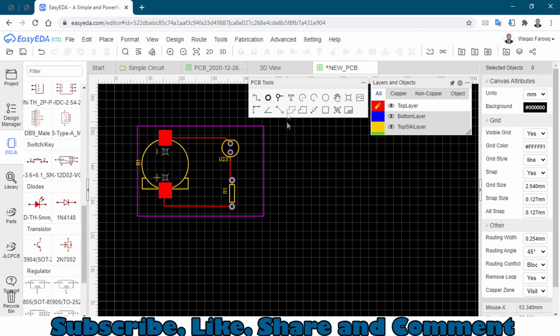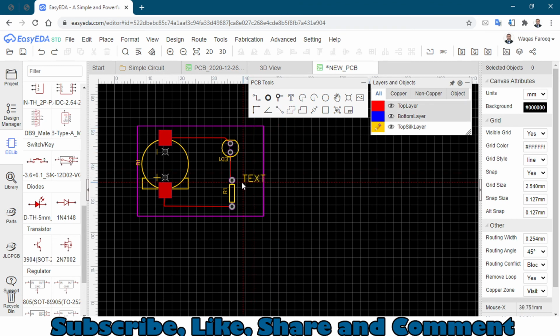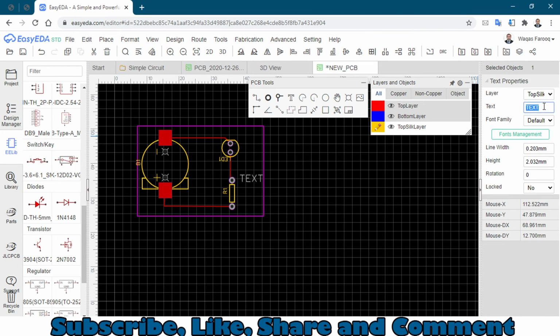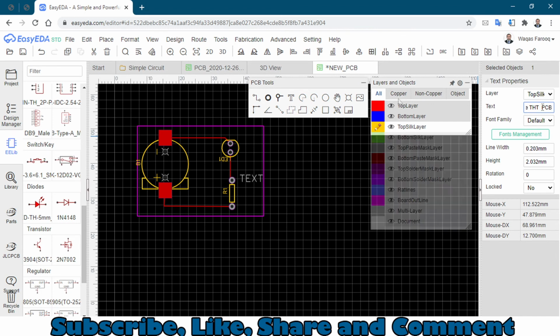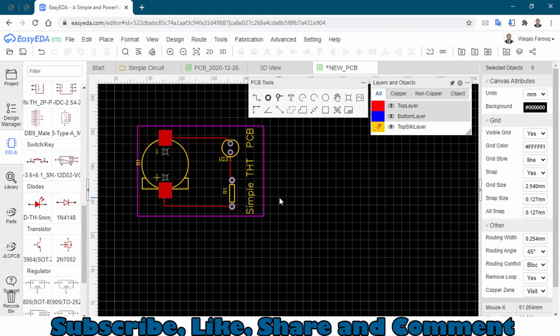Okay, so I will add text again right here, but this will not be visible because we haven't selected any top silk layer. Click on this. Now click on text, place text here, and change the text to simple THT PCB. We have the text here. Just click, press rotate, and you can rotate the whole text, place it here. Now press Ctrl S to save.